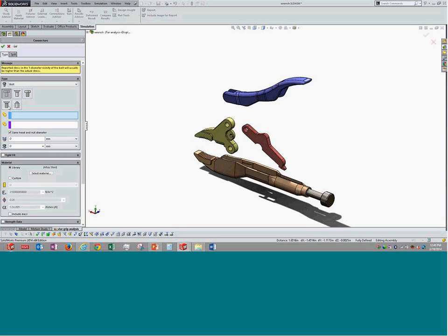When we create a new study, we have an option to export the related settings as they are. In the past, we were required to suppress those bolts or get rid of those bolts and then create the definition for the different bolts in a separate way. That was the approach in the past. However, now we can create them directly. So you can see here we have these different options for bolts.